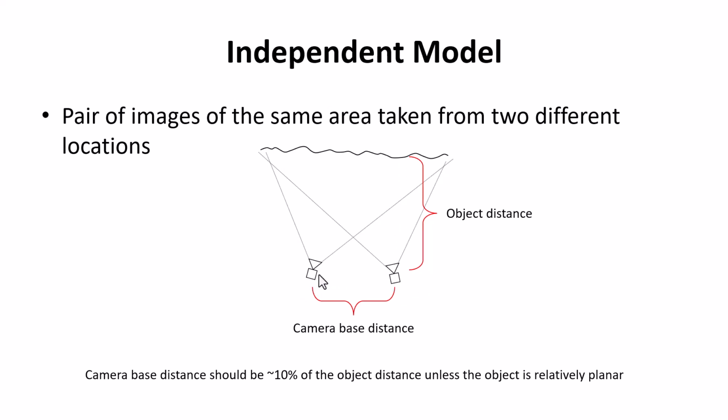Also note how both camera locations are, if you connect a line between the two camera stations, it's parallel to the object of interest. That's best practices. You want these to be roughly parallel to the object of interest. There's no point in having this camera station located way back here and this one close. Having one very close, one far away is really poor practice for gathering those images.